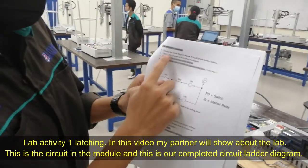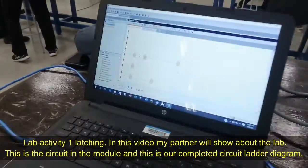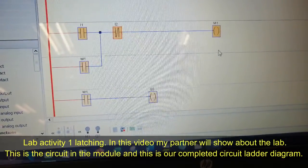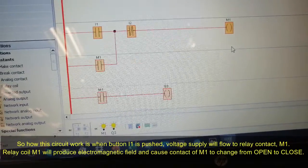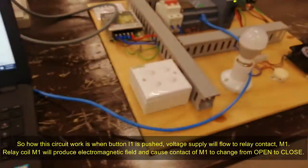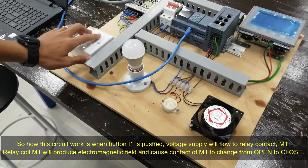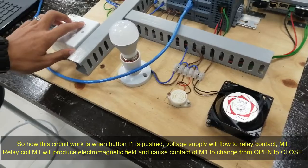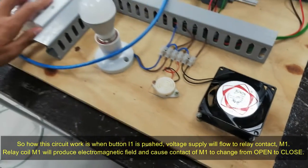Lab activity 1, latching. In this video, my partner will show about the lab. This is the circuit in the module, and this is our complete ladder diagram. So how this circuit works is when button I1 is pushed, voltage supply will flow to relay coil M1, which will produce an electromagnetic field and cause the contact of M1 to change from open to close.